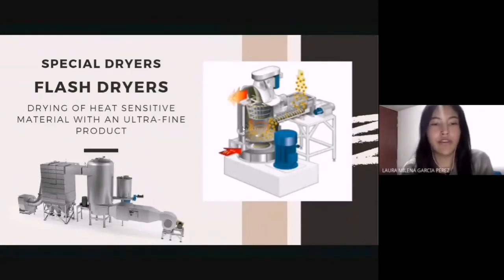The dry particles are transported with the gas stream to the top of the dryer, where a separator classifies them according to their weight. Those that are too large or too wet return to the lower parts, and those particles that pass the classifier are transported with the extracted air to a dust-air separator system such as a cyclone.